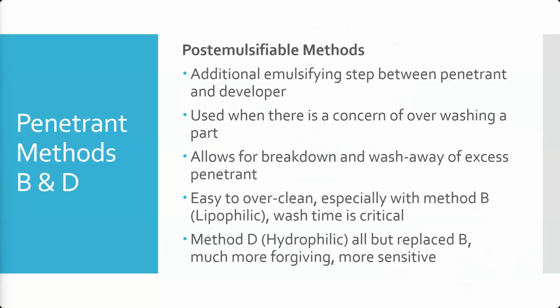B and D I'm going to put together because they're known as post-emulsifiable methods. Okay? And so what this means is, hopefully everybody's familiar with the fact that oil and water don't mix. And under normal circumstances, water does not wash away oil. Right? Now, our method A, water washable, has an emulsifier actually in the penetrant.